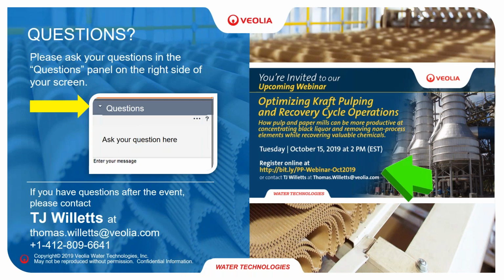Calcium and MBBR, you're talking about pumps, but if we have high calcium levels in the wastewater, we are very careful with MBBR, because if you get precipitation on the carriers, they will stop moving. So we are very careful to look through what kind of calcium specification there is. We have some carriers that are less sensitive to it, but still we need to avoid very high calcium levels in the wastewater. Then we shouldn't go for this, I'd say.